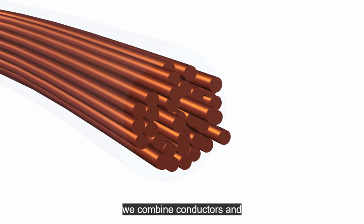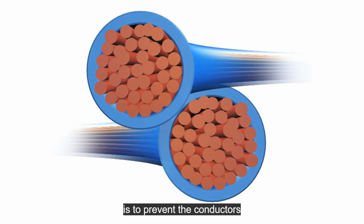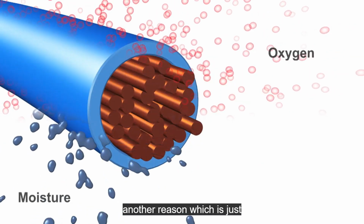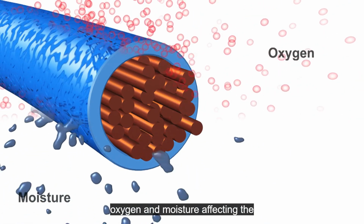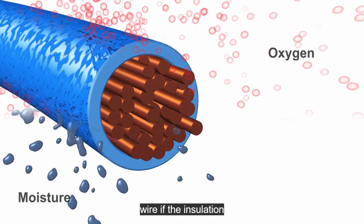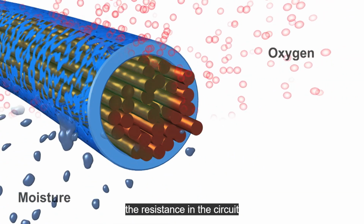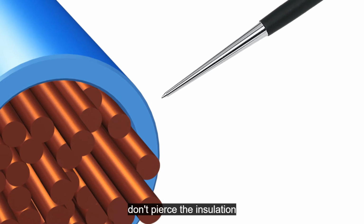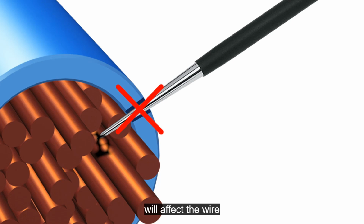We combine conductors and insulators in the wiring. One reason this is done is to prevent the conductors from touching each other. Another reason, which is just as important, is to prevent oxygen and moisture affecting the wire. If the insulation is damaged, the wire will start to oxidize, affecting the resistance in the circuit. When doing electrical testing, don't pierce the insulation to take measurements, as this will affect the wire.